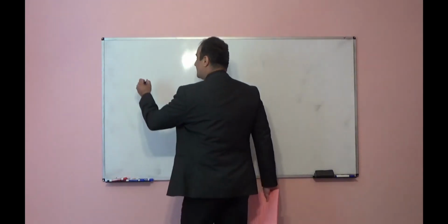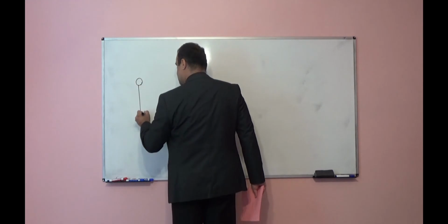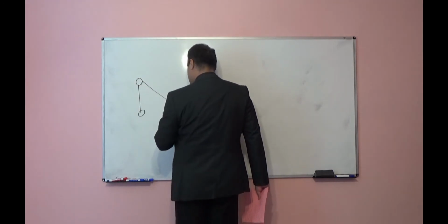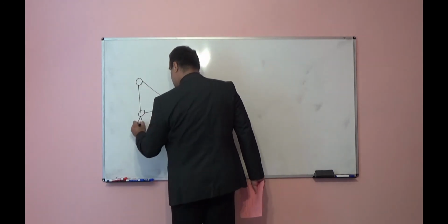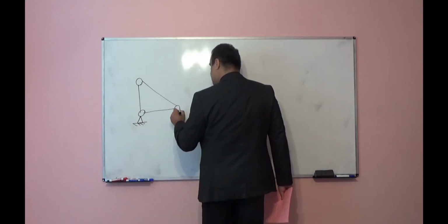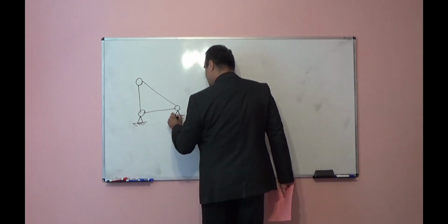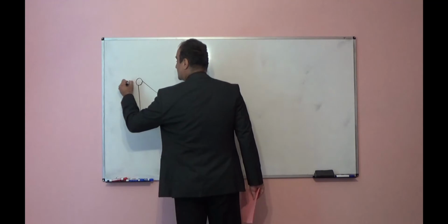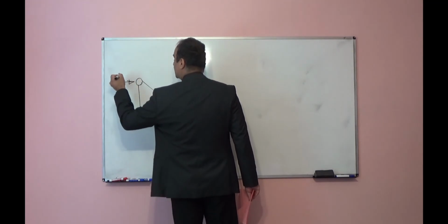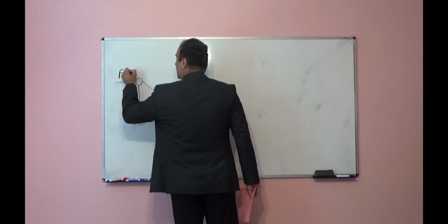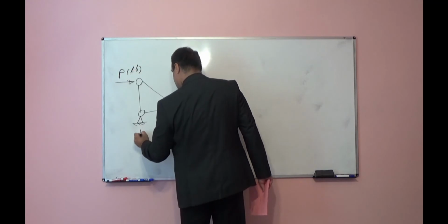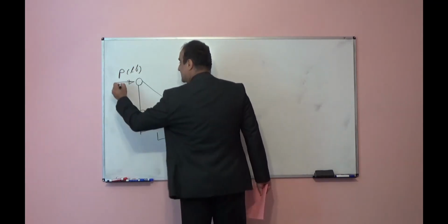So if we have one simple truss, the simplest truss should include 3 members, and using one pin support and another roller, I attach it to the ground and subject it to an external load, for example, P pound, and the member length, this is L, for example.